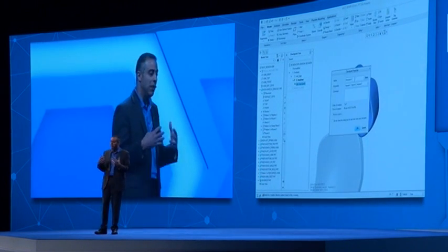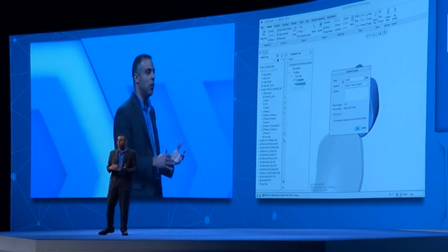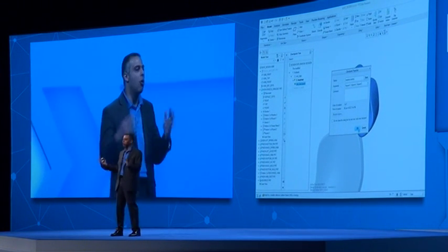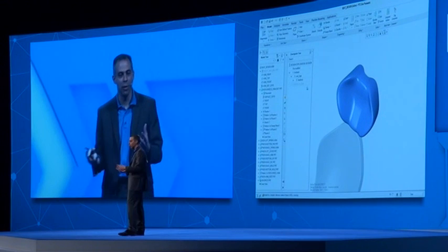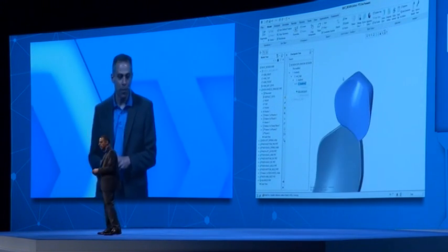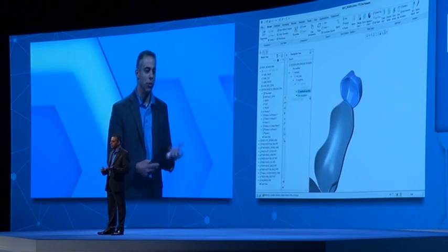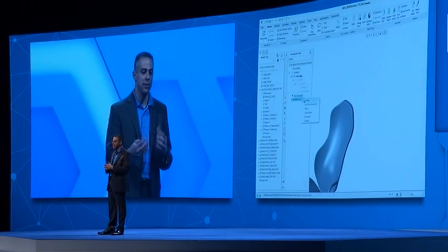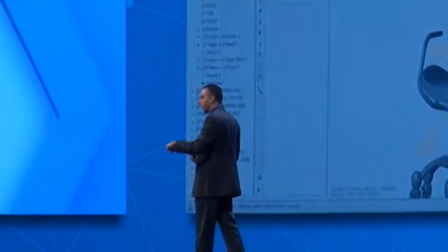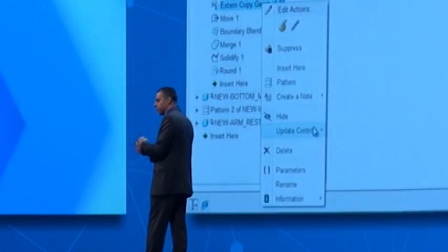Okay, so you can do this with freestyle. You can do this with really any core modeling mode: part mode, assembly mode, sheet metals, mechanisms. It all works in Design Exploration Extension. It's right there in the core of Creo Parametric. Okay, and now you can see how easy it is to cycle through these different checkpoints and see the updates dynamically in your session. The one last element that I want to share with you is this change consequences issue.